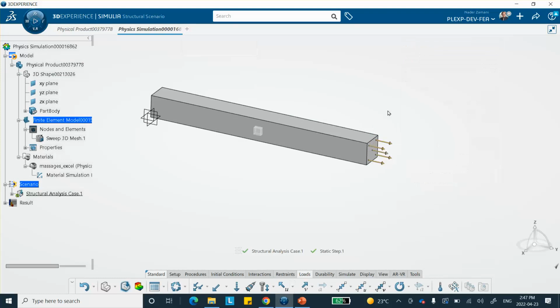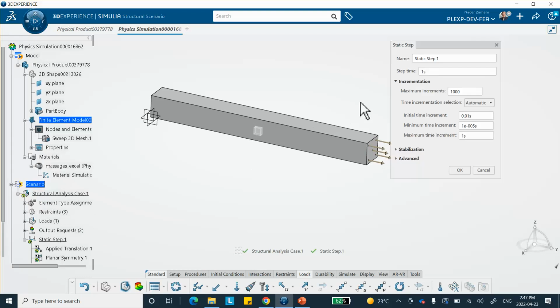The only thing is that my time, I have to go change it here. So under static step, because if there's any meaning to using the data and interpolating, at least the strain rate must be meaningful, okay? So it's 2 millimeter over a 5 second interval. Otherwise, this does not make sense, okay?